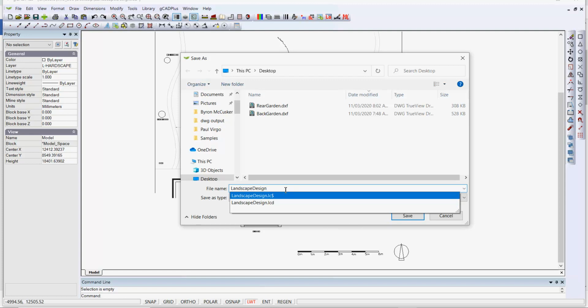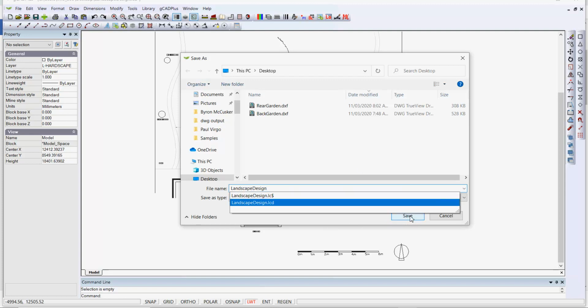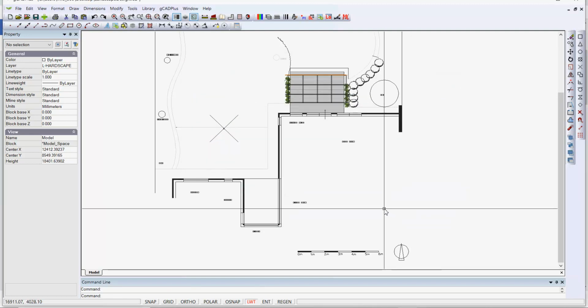And we're going to export it, of course, as a DXF file. So that file's now been written from here and is now in a form that some versions of SketchUp can accept it. So let's swing to SketchUp and see if we can import the base information.